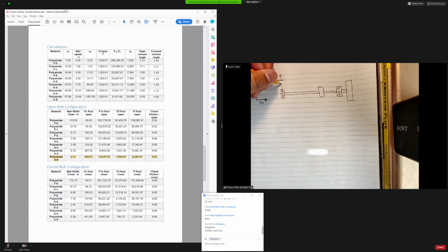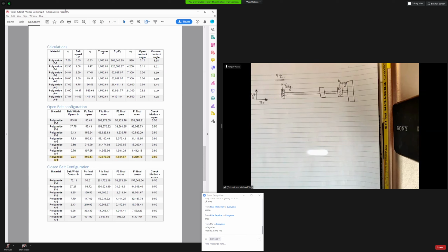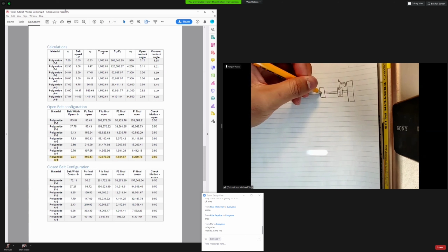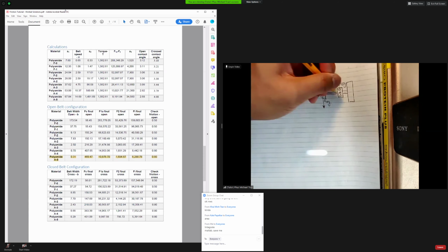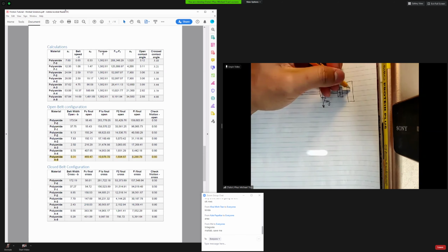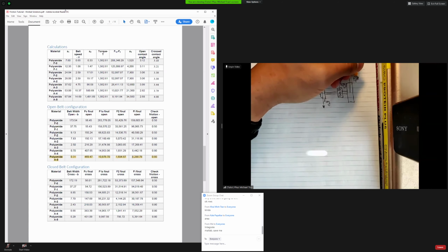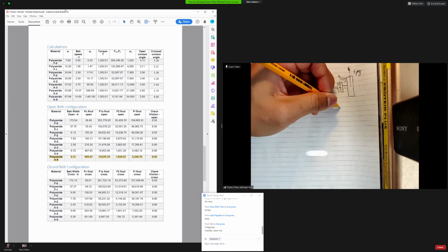So set up the bearings the same way. FB1Y, FB2Y, and the direction of the gears is going to be the same, downwards, or in the direction at least. But your pulley, because we have an 800 kilo pulley, the reaction is going to be that way. Dimensions the same.